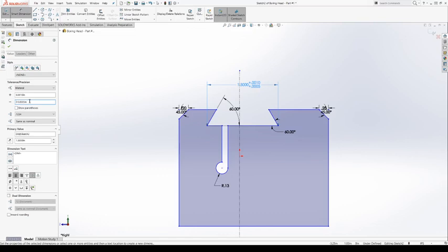When we look at a tolerance and it's a plus 1/2 minus 0, that's kind of telling us the same thing, right? We want to make it just slightly bigger than 1.5 inches. If we make it any smaller than 1.5, it's not going to be big enough. This is basically saying the same thing, but this kind of makes it easier for the engineer because then they don't have to do math on this 1.5 inches. They can just leave it 1.5 inches and say, this is what I intend for this part to do. Maybe my other part is minus 1 minus 1/2, right? So a little different than what we're used to, but like I said, it's actually a fairly common way.